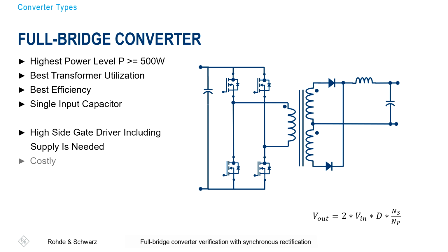The high-side driver problem is basically the same here. So we have it now 2 times, but when you can solve it once, it's not a big deal to do it a second time. But of course, this system is really costly because we have thrown a lot of silicon into the circuit, and the complexity is also increasing.